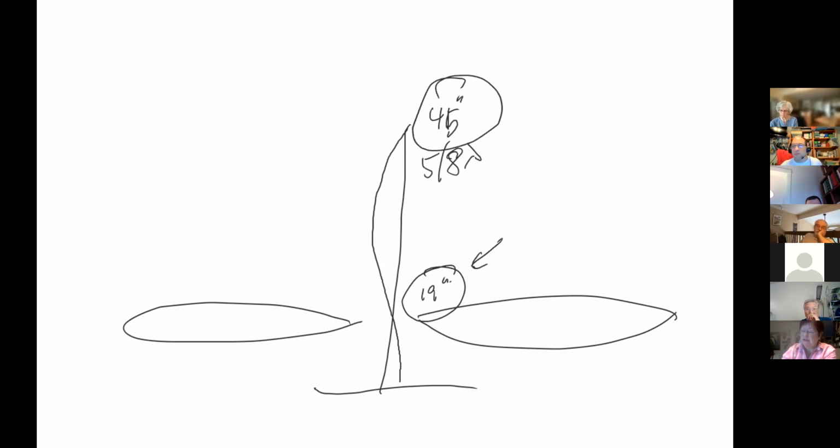What did you say about the lower angle? It has a lower angle of radiation. And where are most of the people you want to talk to if you're in your car? Are they way up in the air or are they along the ground? They're on the ground. So a lower angle of radiation is typically better for mobile operating.